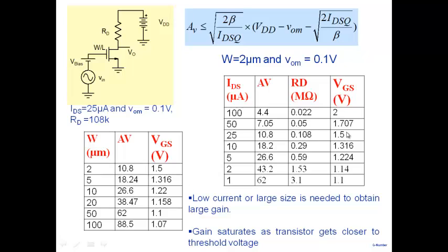Now both of these are problematic. Why? Because making large resistors is difficult. If I'm making a circuit like this on a breadboard or on a PCB, well, a mega ohm resistor is very easy, and you can easily make this particular amplifier. But if you're making it on an IC, making large resistors on an IC is difficult, and therefore this is problematic. You can't easily make a 3 mega ohm or a 10 mega ohm resistor on an IC because the size of the resistor becomes large. Okay, so that's something that you would like to avoid here.